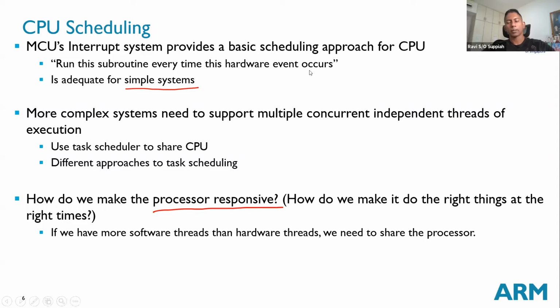Okay, so in the hardware sense, we are limited, right? Because when you choose a microcontroller, you are already limited by how many timer modules it has, how many GPIO interrupts it has, and so on. So the next best option is to look at it from the software perspective. Instead of just relying on hardware concurrency, why don't I do it from the software perspective?